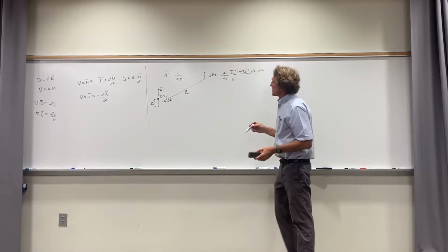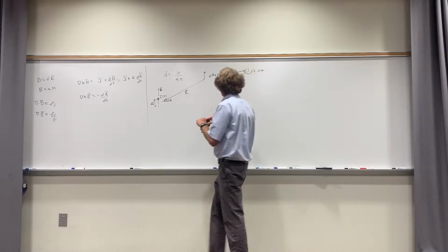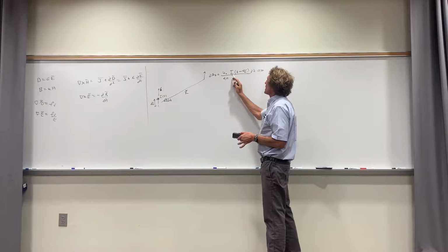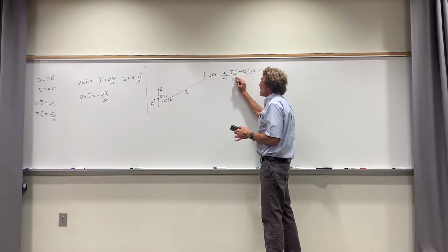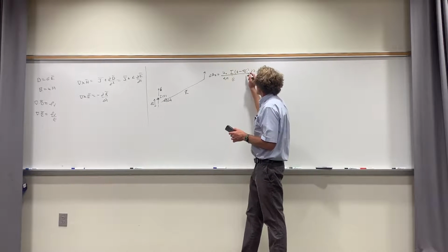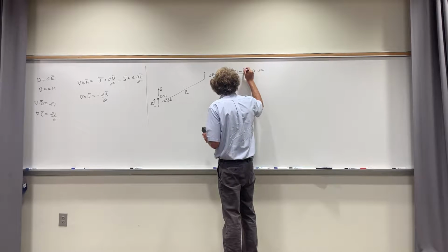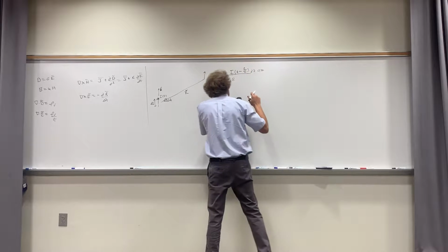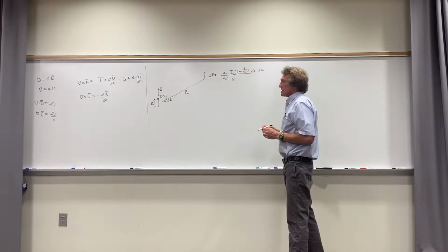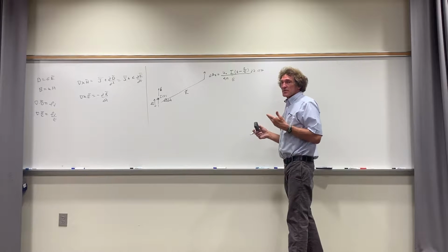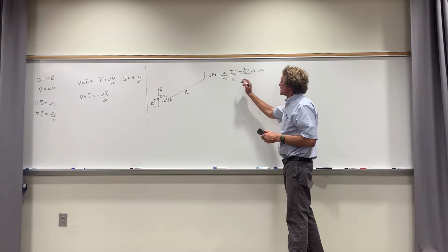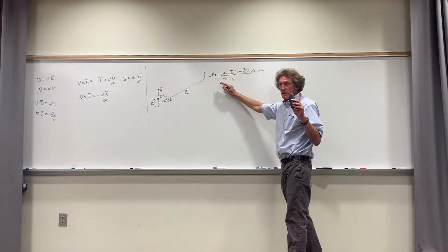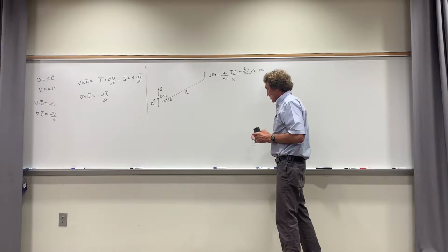So try to appreciate one thing. This magnetic vector potential I'm showing you here is the differential magnetic vector potential, mu I, and then it's the value of I with a time delay of t minus R over c. That's the speed of light time delay. I hope you can appreciate this. Times dz a_z. This doesn't mean much to you right now, but here's the beauty of this. This differential vector field is only in one direction. It's in the direction of the current element causing it. And this becomes important in a bit.